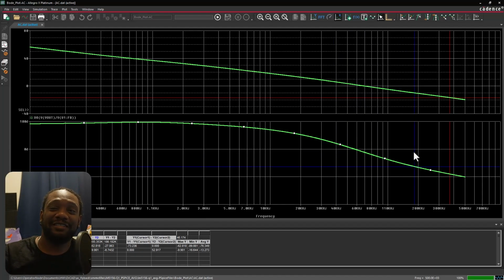What that would look like is, because the phase is so close to 180 degrees out of sync, the controller may become underdamped. You may get oscillations on your output voltage, instead of a quick little ripple with pretty much zero oscillations, or just a small ripple. You can get oscillations if your phase is too close to 180 degrees, and if your gain isn't large enough, and so forth. So you really need to check that. It's that phase that will show you the real stability in that loop, from just one AC analysis.